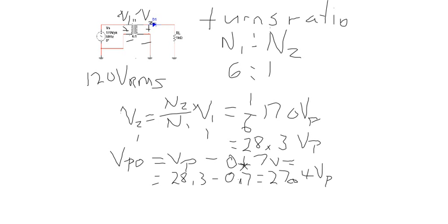Now that voltage is going to look like this, which doesn't look a whole lot like DC. DC is a flat line, remember? So to get closer to DC, one trick we can do is to add a capacitor in parallel with the load resistor.